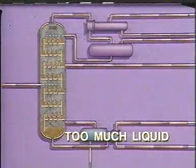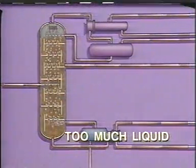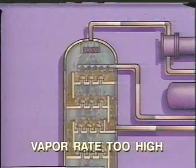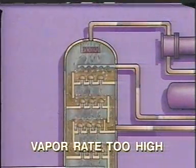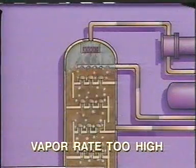When the capacity of the downcomers and trays is exceeded, liquid backs up in the tower and the column floods. A vapor rate that is too high can also cause flooding. The pressure from excessive vapor rates resists the flow of liquid down the tower. If this pressure is high enough, liquid will back up the tower and flooding occurs.